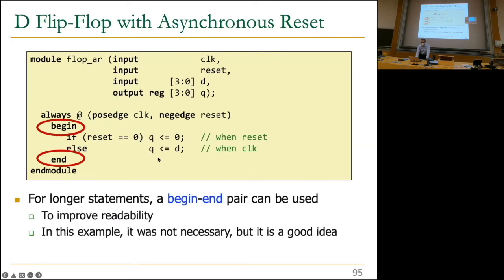So let's take a look at what happens. Clearly I've used begin and end here, as I mentioned earlier. For longer statements under an always block, you use begin and end. In this example it's not necessary, but it's a good idea in general.